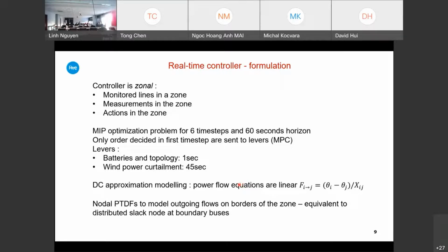But for the moment, we need to rely on very high quality software that we know works, or we understand why it doesn't work. And for the moment, that is not the case with AC optimal power flow. Even with interior point methods, sometimes we don't have results and we don't know exactly why. So for the moment, we cannot in real time use anything other than linear programming or mixed integer linear programming.